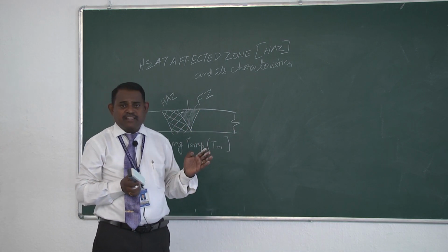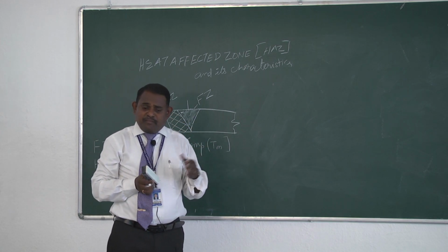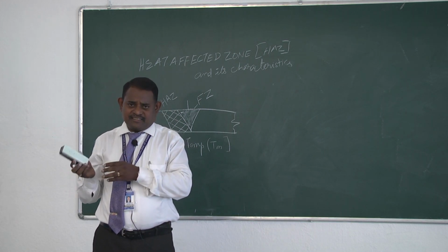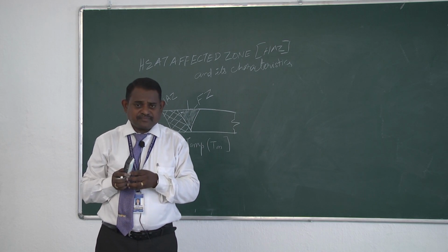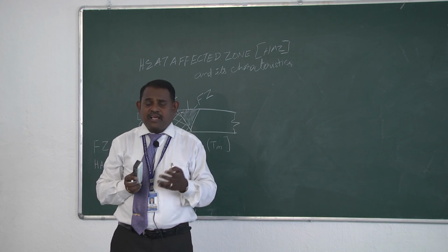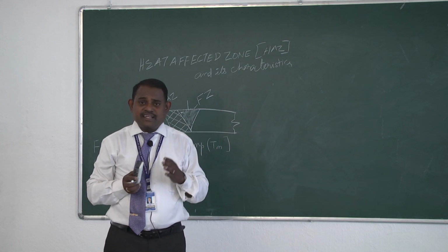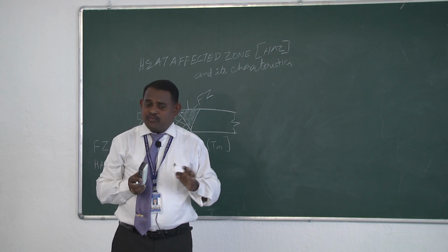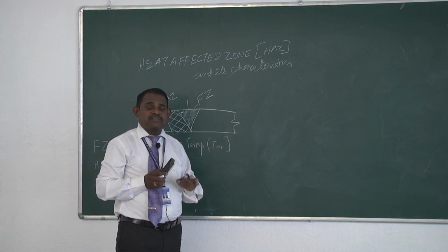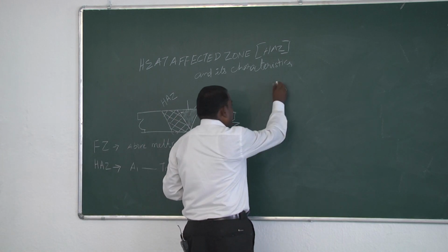So such a kind of material, when it is being welded, will behave in a different way in the heat affected zone microstructures. And some materials may not necessarily have temperature dependent phase transformations. And some of the materials will be heat treated to achieve higher strength, like your aluminum and other magnesium materials. They are strengthened by the precipitate strengthening mechanism. So we have 4 different kinds of materials. All those materials will have different properties with respect to welding. So we will see one by one.